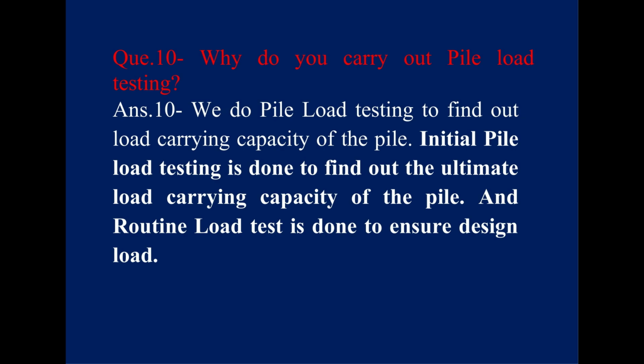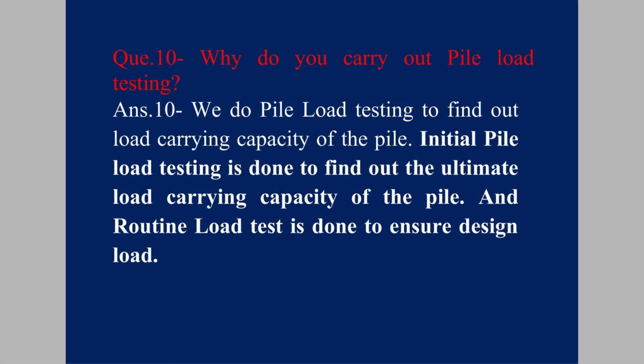Question: Why do you carry out pile load testing? Answer: We do pile load testing to find out load carrying capacity of the pile. Initial pile load testing is done to find out the ultimate load carrying capacity of the pile, and routine load test is done to ensure design load.